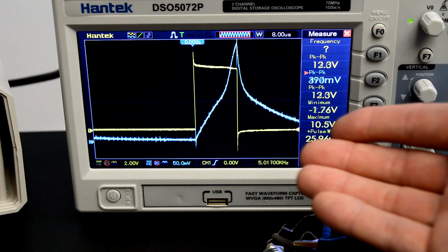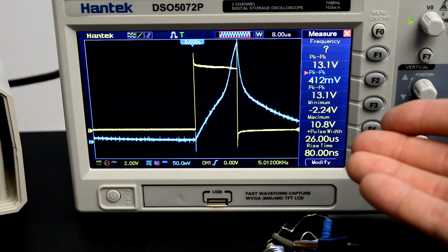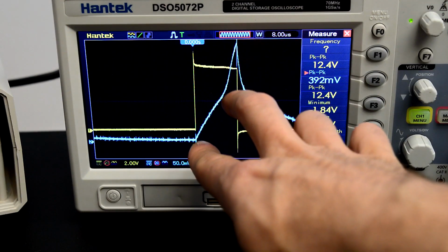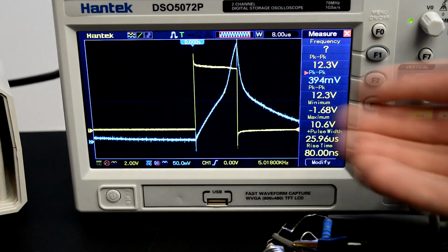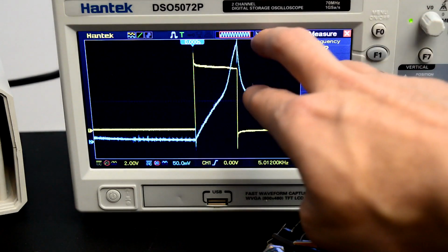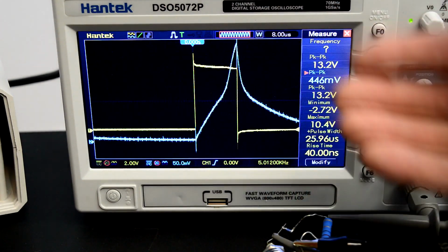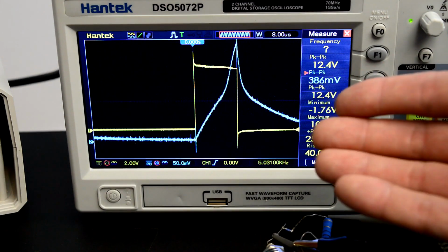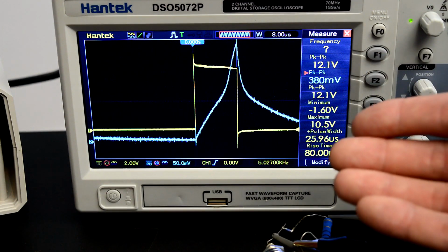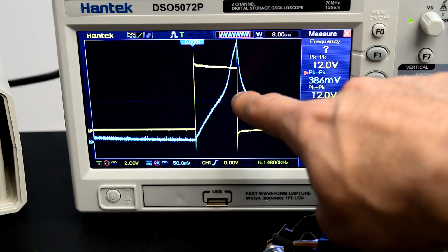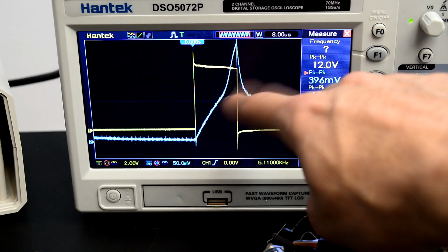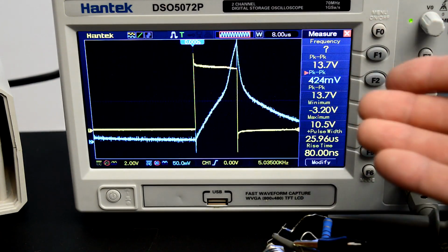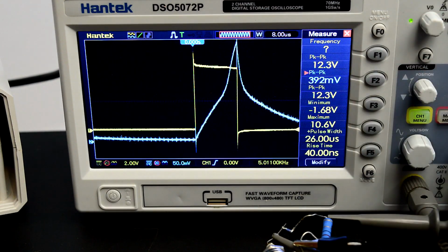So what we're seeing is that the inductor is changing its inductance. So the first slope corresponds to the initial inductance of the inductor of 680 microhenry, and then the second slope, which is much steeper, corresponds to a smaller inductance. So this is basically saturation in effect. After we exceeded a certain current going through the inductor, the core saturates and the current shoots up because it no longer has the same inductance as before.